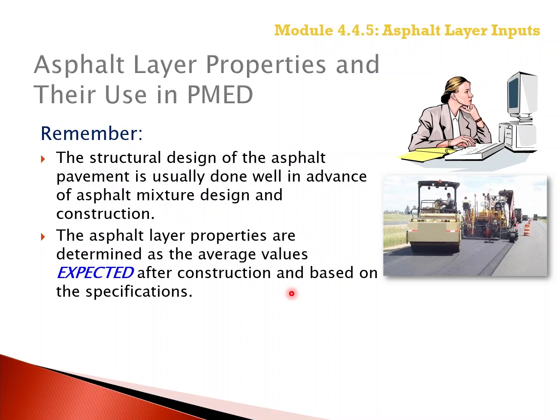For the different asphalt mixtures specified by the agency and placed by the contractor, the average values for the asphalt material input variables that meet the construction specifications and were found to be acceptable should be determined from the historical or previous year's construction data.